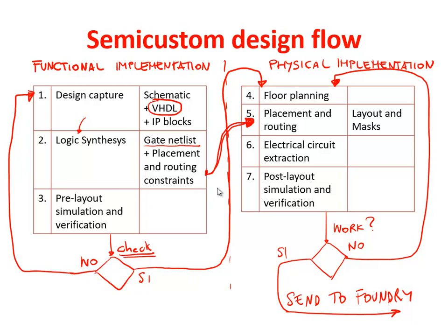important. Of course, I must say that this post-layout verification is only possible if the circuit is not too complicated, because otherwise it's really not doable. It's very often done for communication circuits, because they typically push the technology to high performance, and it's important to verify if physically this can be obtained. But for large microprocessors, it's very hard to do it for the whole chip.